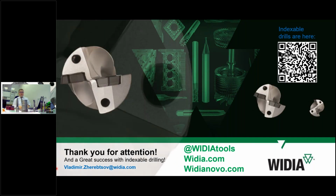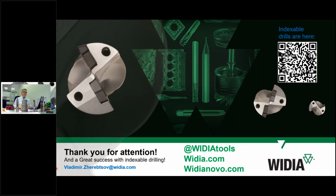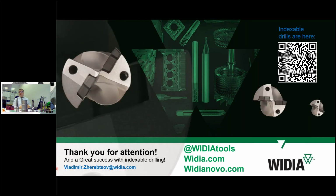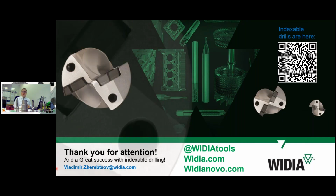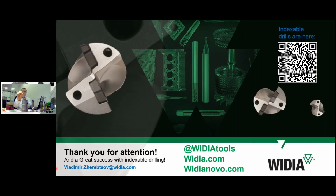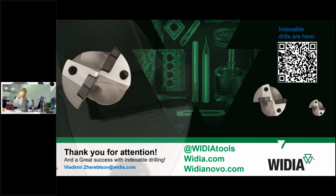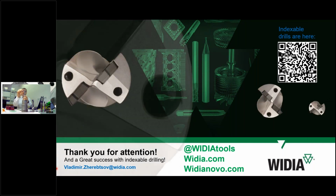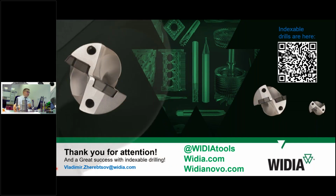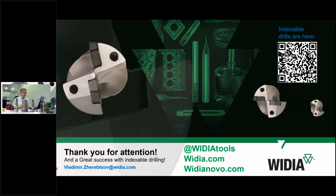Yeah, because we didn't talk a lot about tolerances today. We just mentioned it, but for sure, modular and solid are much more precise. Also, we didn't cover the chip control, which type of chip can be produced by central inserts. In the beginning, it's like a Christmas tree, but it should be middle segmented. And from the periphery, it's like from turning inserts, it should not be a problem. I don't have a slide here and don't have time to touch this, but it's maybe a second topic I will cover in more detail next time.